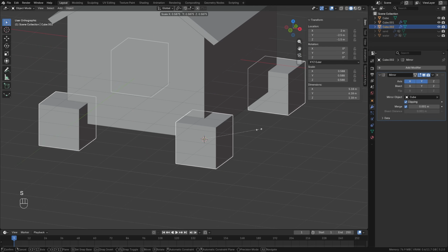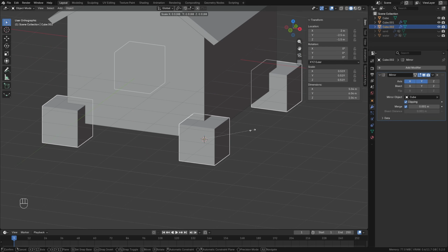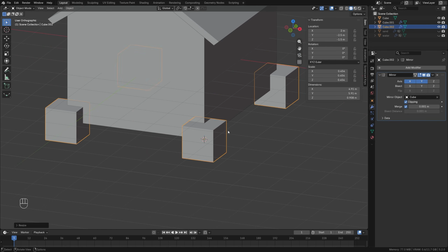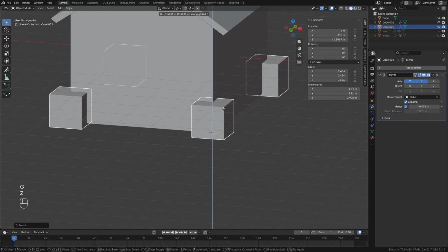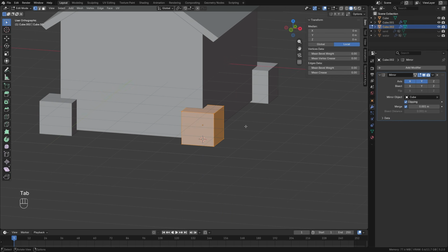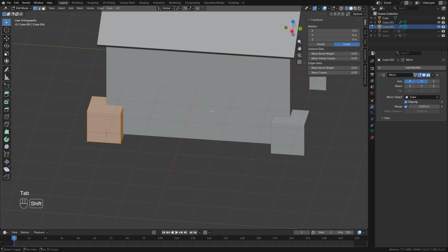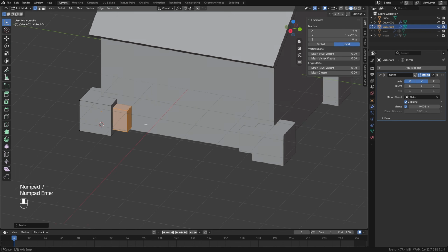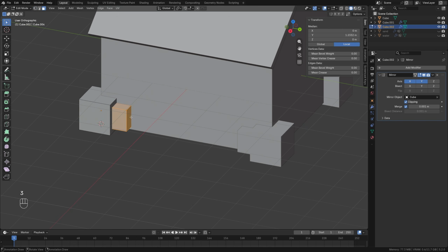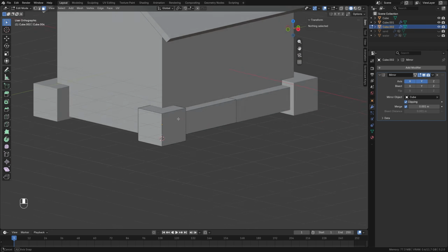Well, first we make them a little smaller. Again, the proportions, if anything, we will edit. Well, roughly in the following way. Possibly, let's also raise it a little bit up. And now in Edit Mode, we duplicate this cube along the Y-axis a little to the side. We press S 0.7 and enter. In this way, we reduced it a little. And now we select this front face here. We press G plus Y and shift to the side, and then X and faces to delete that face which remained for us in the center of mirroring.